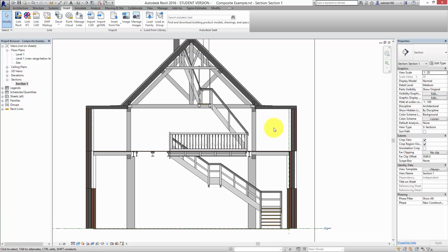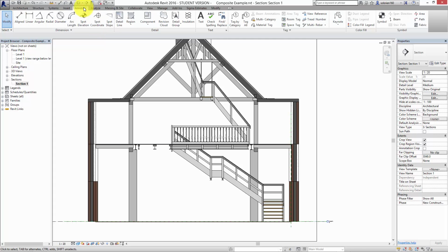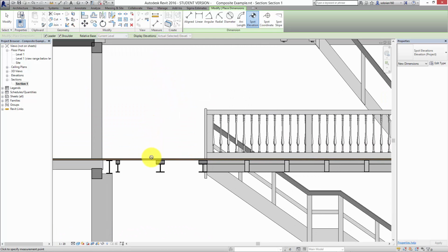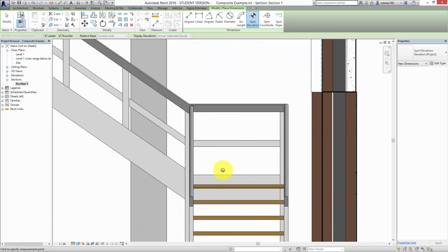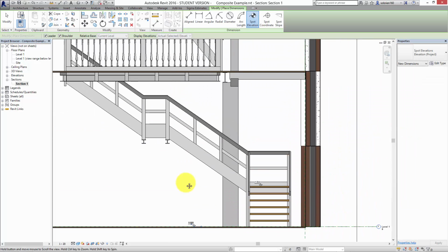With a historical drawing, often you get different levels in different positions, and the model, if it's well measured, will take care of all that for you. But we also need to annotate that. So we can go into the annotate tool here, and this is for when the model is finished. The annotate tool is actually the main thing you want to use from then on. We can click on spot elevation, and if I lay that on top of the floor here, you see it starts to give us an actual value for wherever I'm placing it. So you can just click it there. You can put another one over here. Anywhere there's an actual place where people will be standing, you can put a level on, so you can always be sure that you've got it correct.